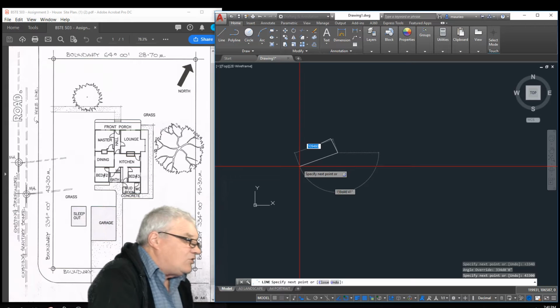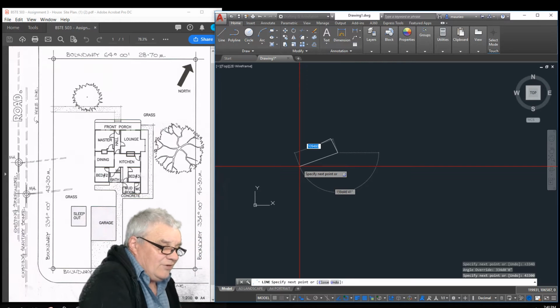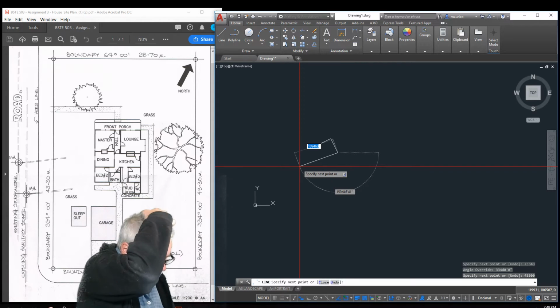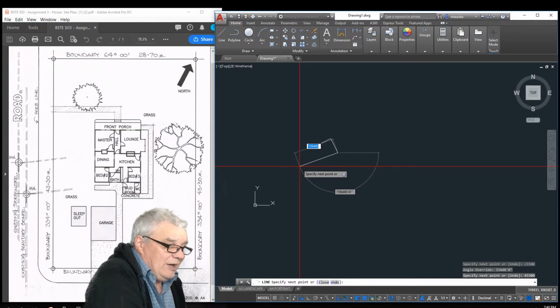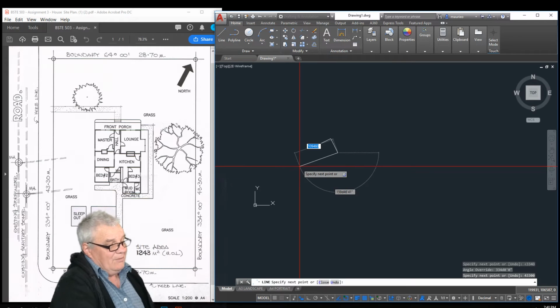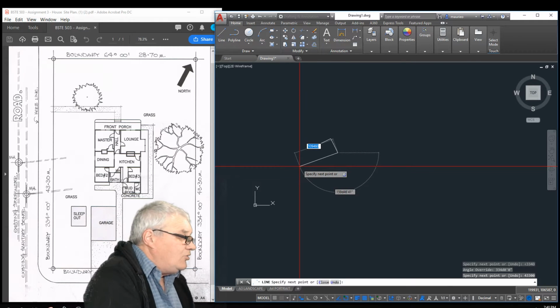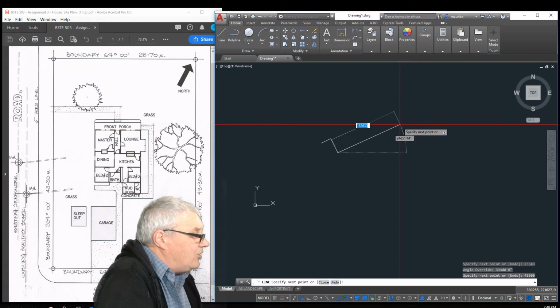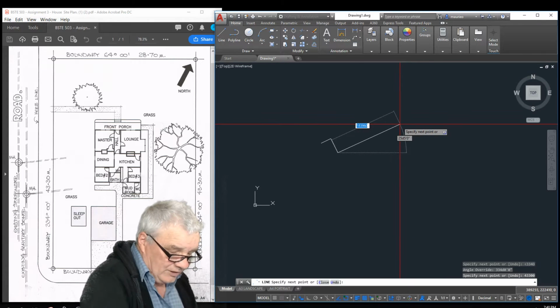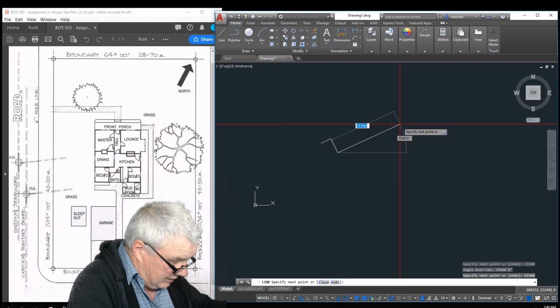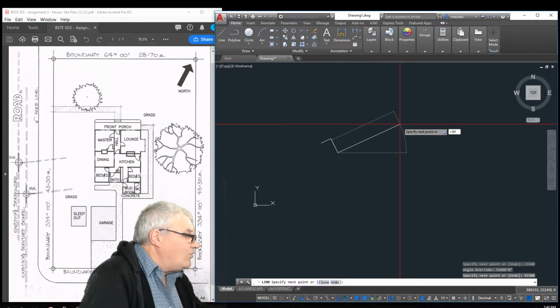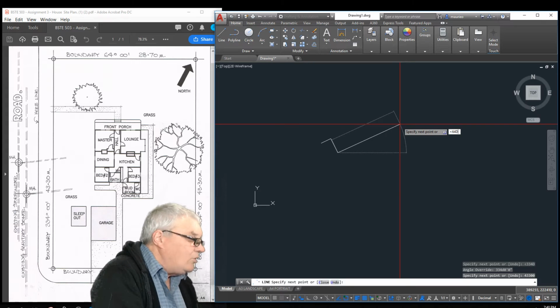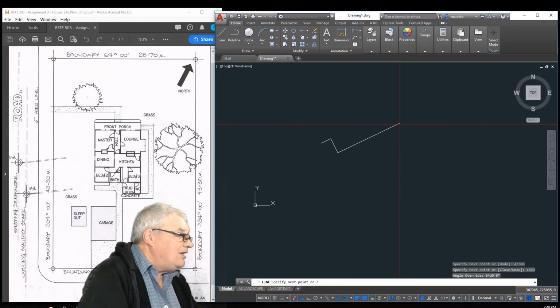Now next one out here, put approximately where it's going to go, and well, it's 64 degrees. Now again, that's not 64. If a bearing is between 0 and 180 and you want to go in a different direction, you add 180, which would be 244. But it doesn't matter, because 64 degrees, as we know, is actually out there. So we can put that in using the shift key there, 64 degrees, enter.